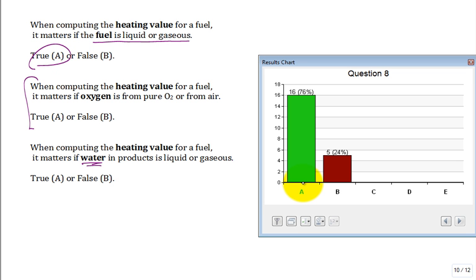This is an oxymoron, condensing furnace. Anybody ever heard of a condensing furnace? You're going to burn propane or methane in your house, and the furnace is going to condense. What's it going to condense? The water in the products that come about by breaking up that hydrocarbon fuel. You get CO2 and you get water vapor.